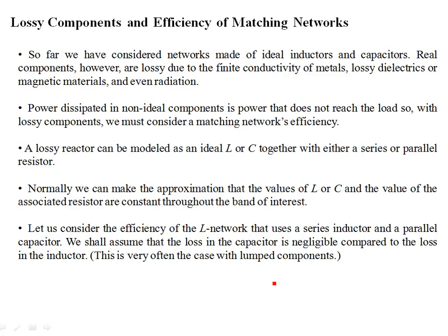Networks, L networks, pi networks, T networks, and the components which constitute such networks between the source impedance and the load, they're all LC elements, lumped circuit elements, and we have assumed them to be lossless. Okay, so for example, there is no dielectric loss in the capacitor, and we have not assumed any finite conductivity of the metal wires in an inductor.